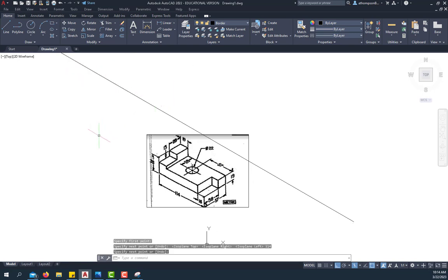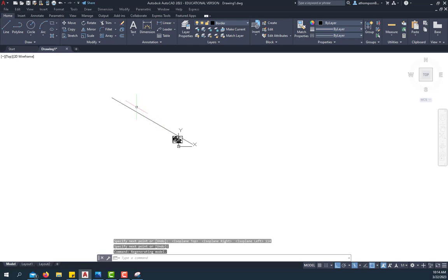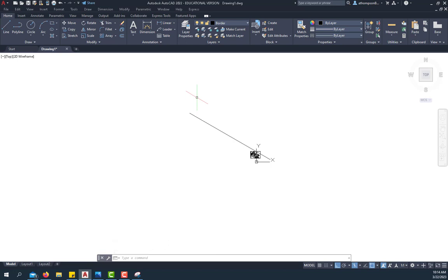And it's going to go off my screen because this is metric. And remember, AutoCAD doesn't understand metric units versus English units. Okay, 1 unit to AutoCAD is 1 unit, whether it's a millimeter or an inch. So it makes everything look really big. But remember, we scale it to what we need it to be in paper space when we print it. So I'm going to take just a second and move this picture over and actually scale it up so you guys can see it now.